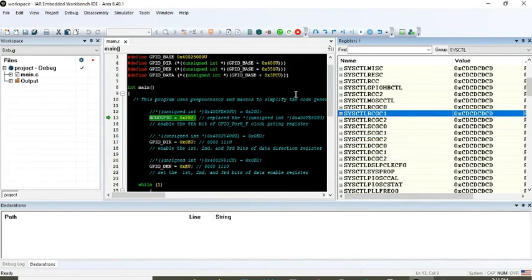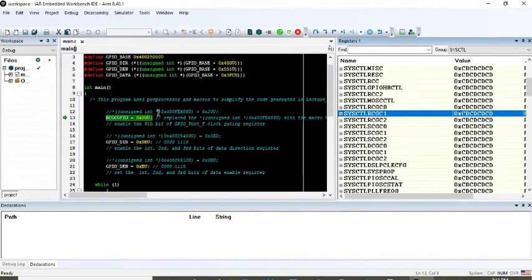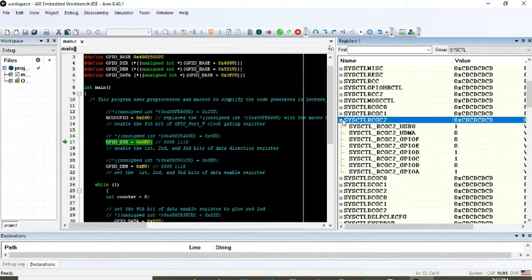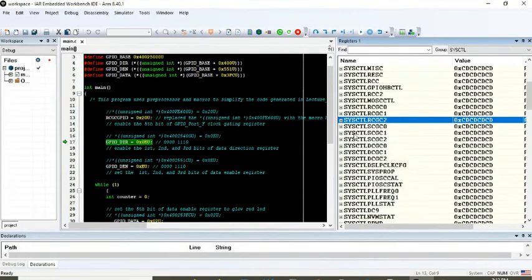things will change. But still, let us go through these details and check whether these registers are changing or not. By default, these are the register contents. And for RCGC, we can keep an eye: whichever register changes will become red. Right now the pointer is waiting here. Go to the next line. So RCGC GPIO, we have entered 20, but here we cannot see any effect on RCGC GPIO.